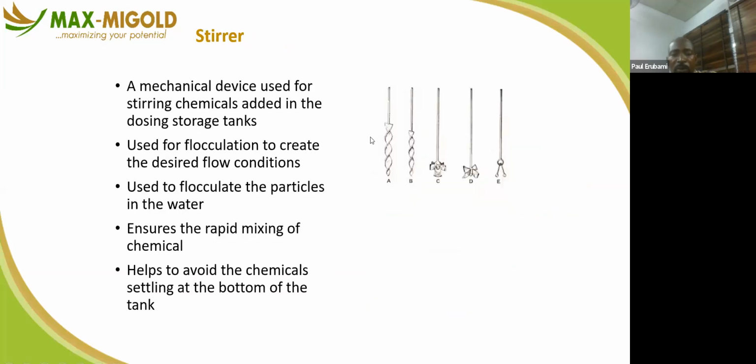These are all examples of a stirrer. I mentioned it in the physical class on Saturday. Now, the reason why you use a stirrer in your water is majorly because chlorine is an incompletely soluble chemical in water. And if you don't use a stirrer, the chlorine settles at the base of the dosing tank. But when you have a stirrer installed, it doesn't allow the chlorine to settle. And when the chlorine settles, you are actually dosing ordinary water into your water system, while you have the chlorine